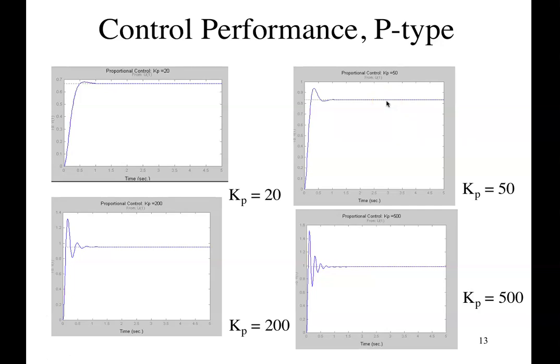So now the steady state error between the output and my input of 1 is less than 0.2. But I can start to see some overshoot. So this value there divided by my final value gives me the overshoot. Settling time is practically fairly similar because of this wobble. This goes up and down and then settles.